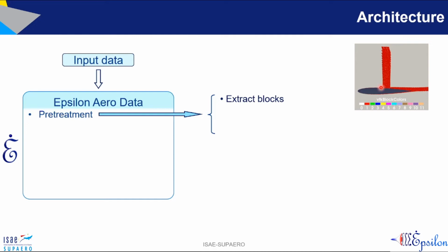This extra block is undesired and is overlapped on top of the grid domain. That's the actual domain. So I had to take away the red part, take that to the trash, and retain only the grid block, block 0, that contains all the physics information. So that's why we included a VTK operation that performs this block extraction.